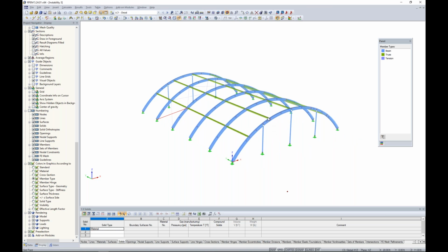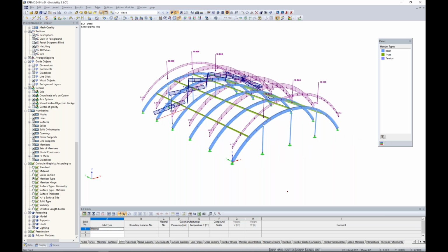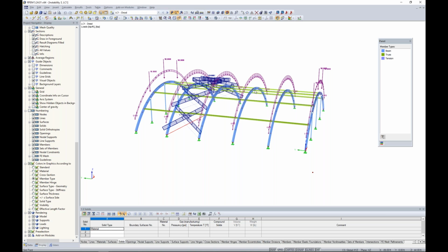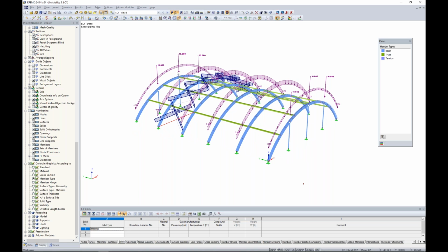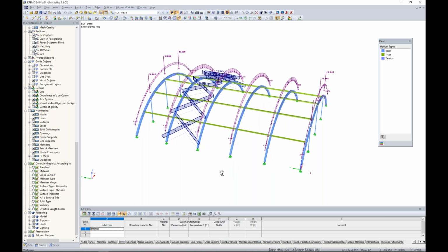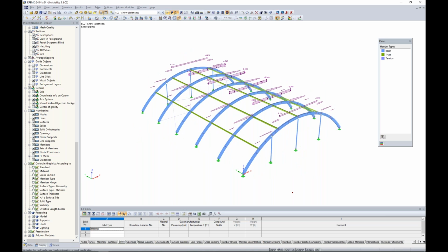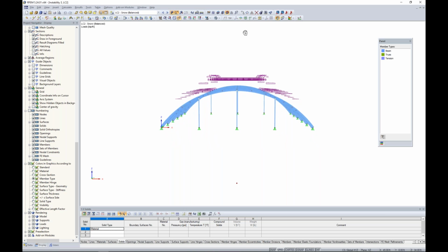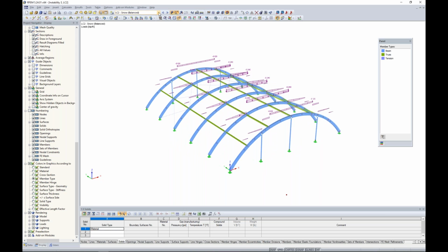Then of course at the front and rear of the structure, we just have these small columns defined here. So looking at my load cases, I have a dead load applied here. So you can see uniform load applied across the top of my members. We have point loads applied to the top of the columns, and we also have a pre-stress applied to these cable elements.